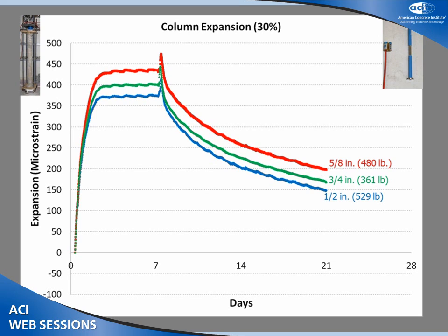The half-inch lies below the other two, and if you notice from the higher pre-compression load, from this result, it's expected that the amount of pre-compression the column receives during early age has a suppressing effect on material expansion as the columns cure.